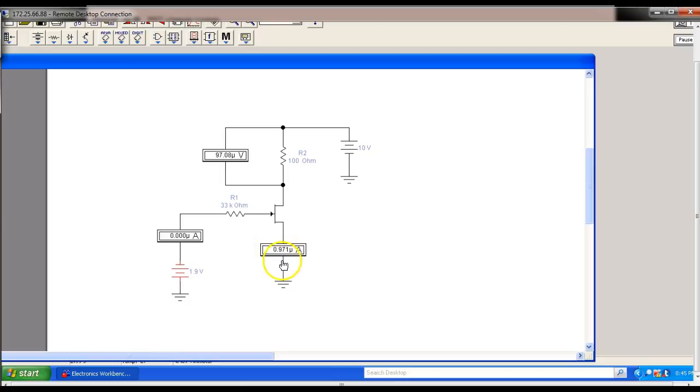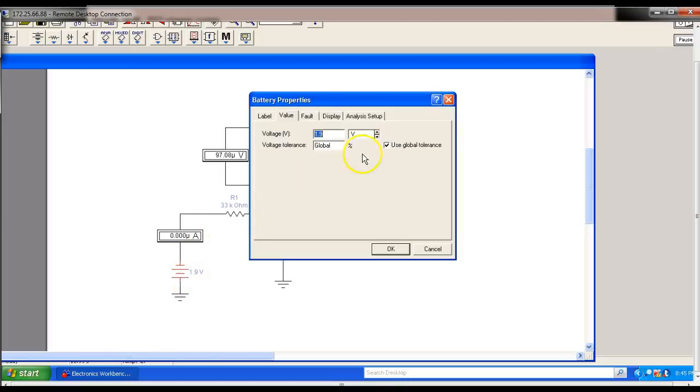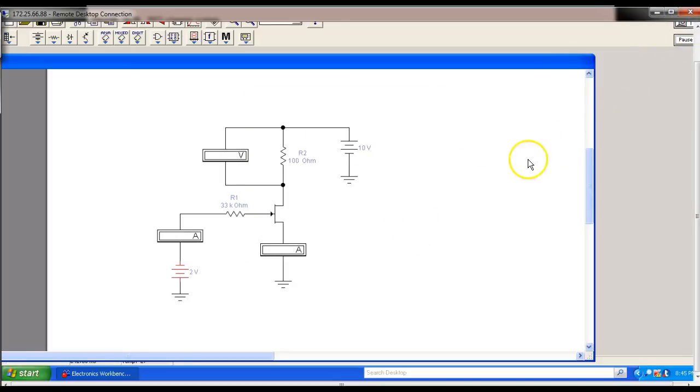And we'll see exactly where this guy actually cuts off. So it looks like 1.2 is the magic number. But notice as I keep increasing my voltage gate to source, the current flow between my source and my drain keeps going down. So we'll go back up to 2. It looks like 2 volts is pretty close to the cutoff voltage for this JFET. And when we turn it back on, we have 0 current. Okay, so right now we are in cutoff.